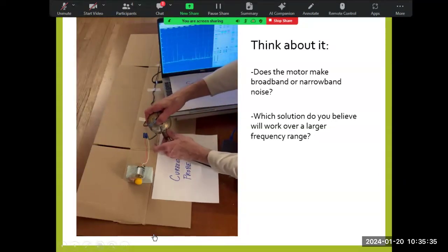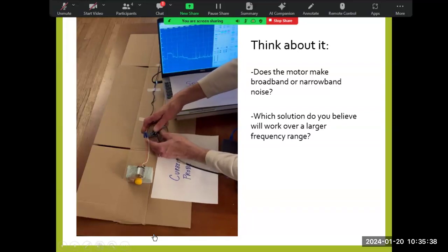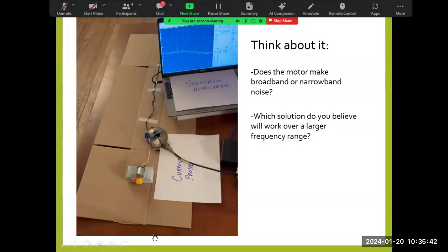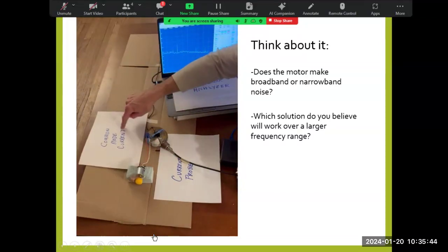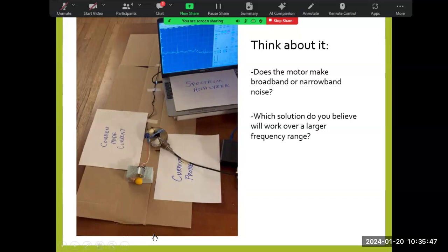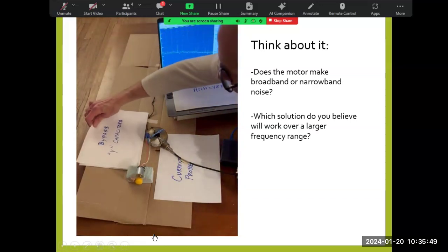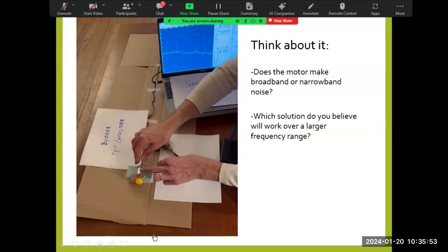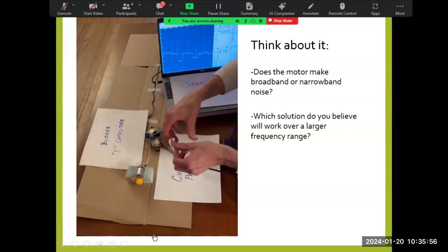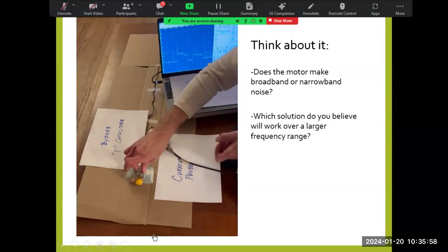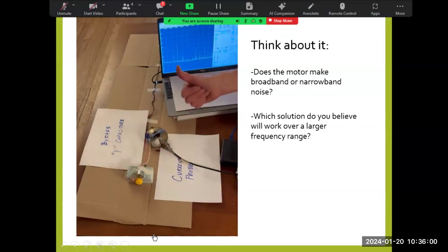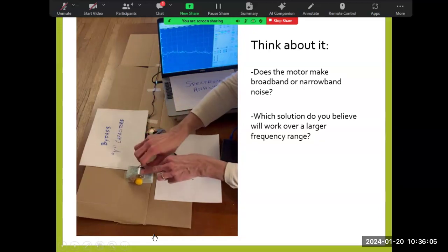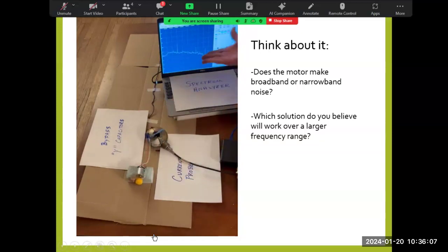Okay, so here you can see the motor running, clamping the probe on the wires. Both wires are going through there. You see the change in the spectrum, measuring common mode current. First, attached to the terminals are two little capacitors. I'm going to connect the wires of the capacitors to the housing to make bypass capacitance. The noise changed, right? It went away. Now I disconnect the capacitors, and the noise comes back.